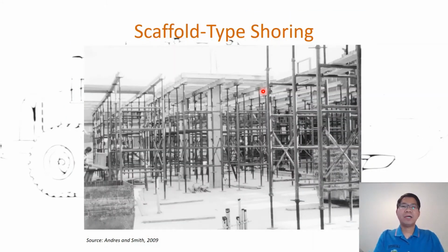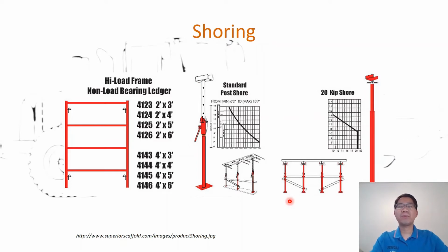And for that, first we talk about shoring. In terms of shoring, sometimes we can use scaffold to play as the shore, as you can see in this picture. This is the scaffold, and we can set it up for placing the concrete on the floor on the top here. This is the floor already placed, and the concrete column, as you can see. And with that we need to have some adjustment for the height added to the scaffold when it is placed as the shore.